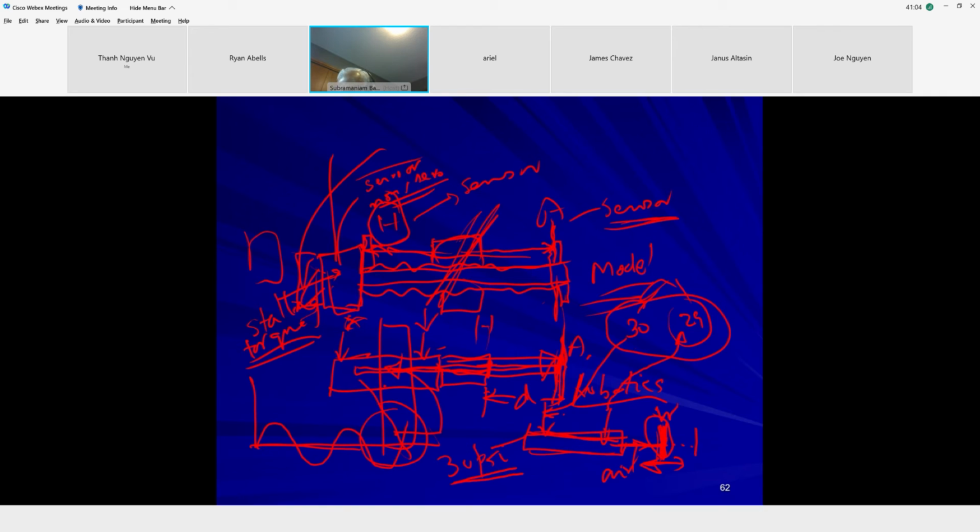not that easily done. But the same principle applies when you apply oil pressure, hydraulics. When your car goes up on a ramp and they push it up with a hydraulic piston, they can control the intermediate position. There is more complex control of the inlet port and outlet port, where you can pulsate and control the pressure, because oil, in comparison to air, is a lot more incompressible, and it is possible to control, right? So this opens up a lot of discussions.